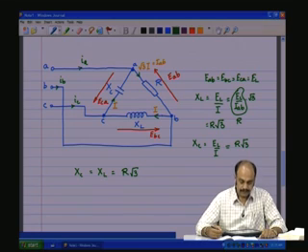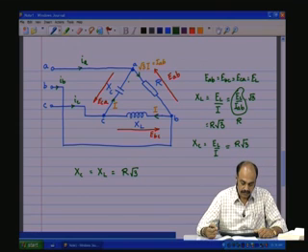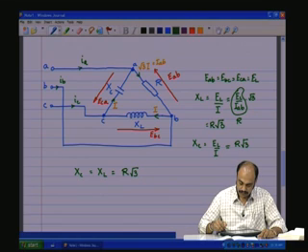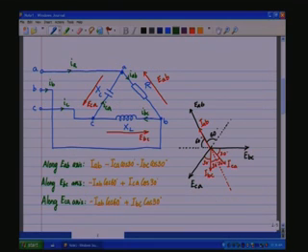And if that is done, then automatically you will have the currents flowing here as this root 3 I and I, and they will be balanced when looked at from the point of view of the equivalent phasor diagrams, because equivalently if IBC is equal to I, ICA is equal to I, then what flows through this, and what flows through this will all be equal.